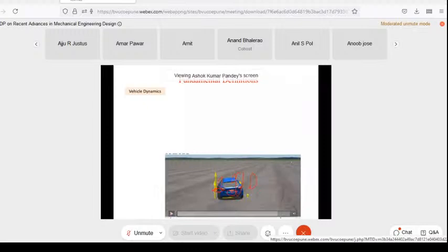You have here the lateral force, and the maximum lateral force will be applied by this wheel at this particular moment, because this tire is undergoing more deformation, and hence the force generated over here will be more as compared to the force at any other wheel. These forces are only trying to keep the wheel from slipping. The moment this becomes zero, your vehicle will slip outward. So we have to relook at all these forces and see how they vary.